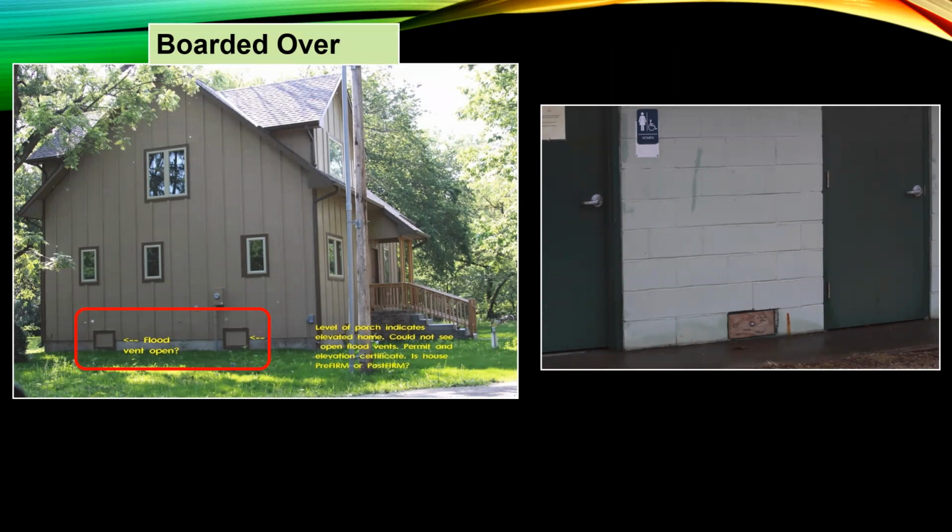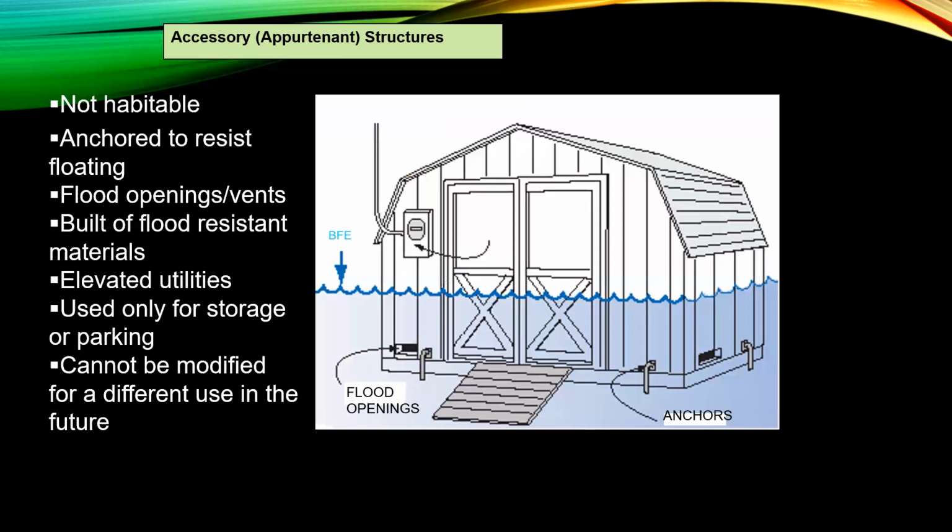So that's another option. They're a little bit more expensive, but they can also help someone avoid needing a major retrofit. So if they don't have enough flood openings built into the enclosure, then they could add these to maybe get to that net opening that they need without, again, doing a major retrofit project to get more openings built into the walls. And then there's another example next to that, with wood covering.